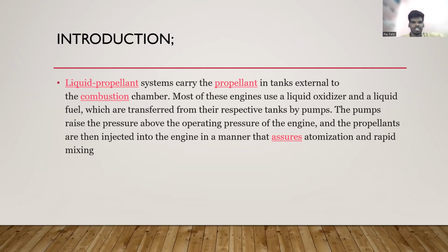Coming to the introduction, liquid propellant systems carry the propellants in tanks and an external combustion chamber. Most of these engines use a liquid oxidizer and liquid fuel, which is transferred from their respective tanks by pumps. The pumps raise the pressure above the operating pressure of the engine. The propellants are injected into the engine in a manner that assures atomization and rapid mixing.